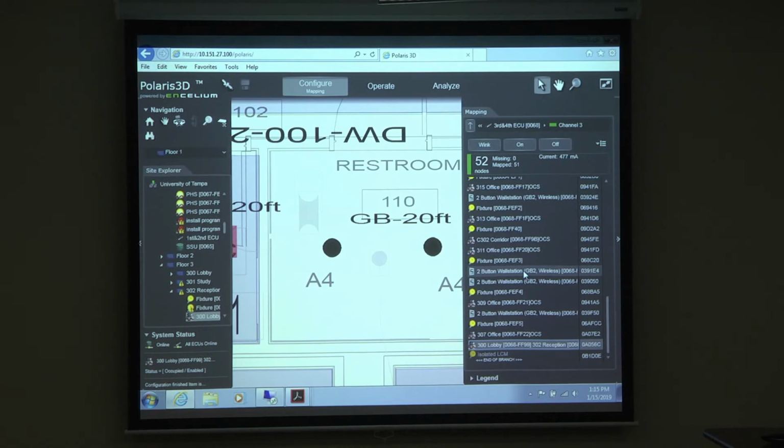But based on my experience, if I have like 10 devices I can put on a channel, I know it'll be fine. The issue comes into play when the building is fully loaded and everything's on, because in some cases someone's going to be on or off. But when it's fully loaded, that's when the devices at the end of the channel start giving some issues. As an electrician, our lighting load is considered at 3 hours full capacity, so you should keep it at 80% of that load for a 3-hour time frame. Got it. Okay.